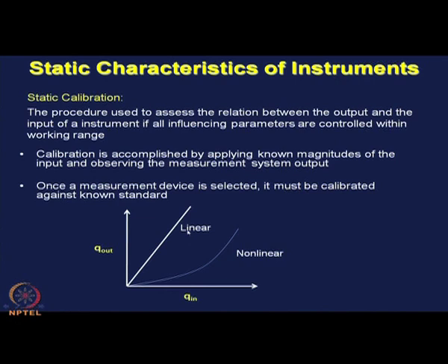Depending on whether the instrument is linear or non-linear, I can have a linear relationship between input and output represented by a straight line, or a nonlinear curve that represents the relationship between input and output. Once an instrument is selected, it must be calibrated against known standard.